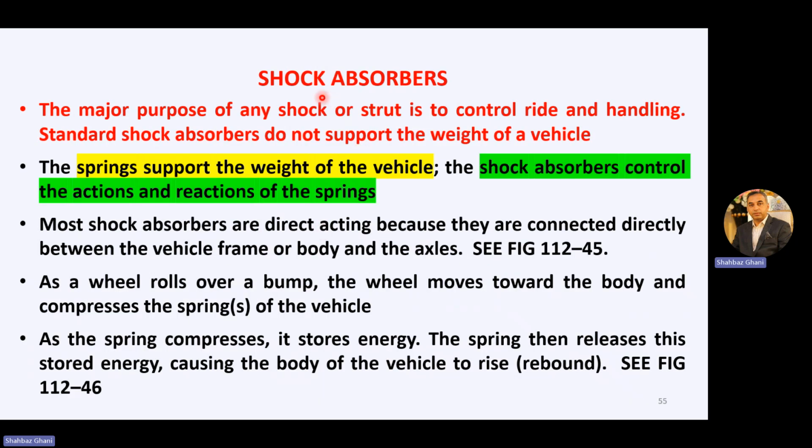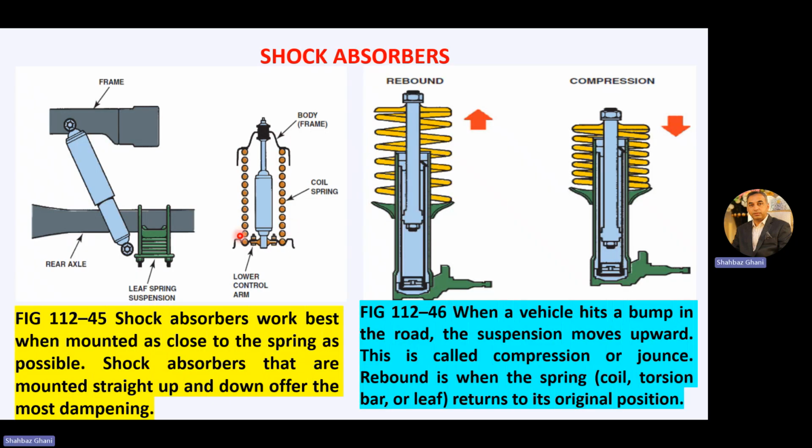Then we have talked about the shock absorber. The basic purpose of the shock absorber is not to support the weight of the vehicle, but the spring supports the weight of the vehicle. The shock absorber controls the action and reaction of that spring. Remember this thing. These are a few illustrated diagrams of the shock absorber, showing what is happening inside.